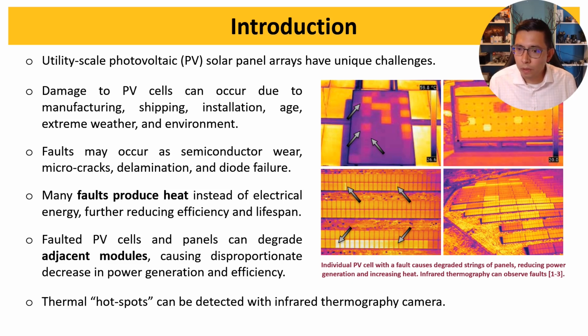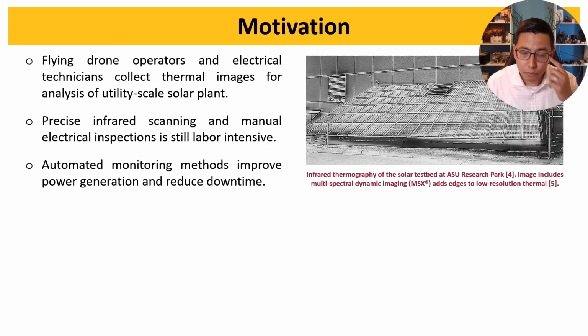This is true of larger scale as well, where several panels might be affected due to the performance of just one of the panels. We want to detect these hotspots with thermal cameras, also known as thermography, and that's going to be the primary method for us to do evaluation of these in the field. For motivation,